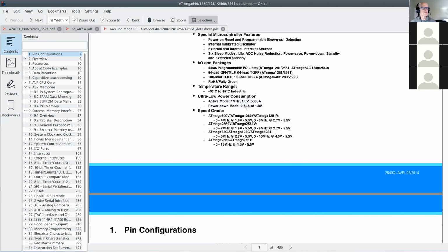We won't get to experiment with that, but we will notice that when we work with timers, there is a register where you can turn on and off all the timers, and each timer requires current. So if you don't need a timer, you can turn it off.